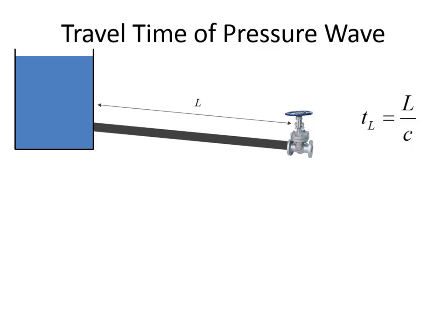And so it's in big municipal water systems that the risk is the greatest, because number one, you're working with large pressures, big diameter pipes, but then also you've got long runs of pipe where closing a valve on some road in a neighborhood, and the shock wave may be going to a reservoir many miles away.